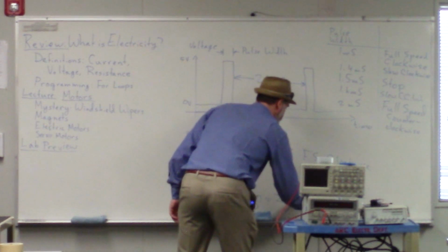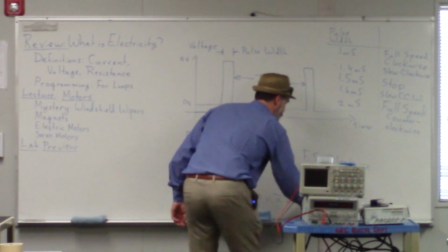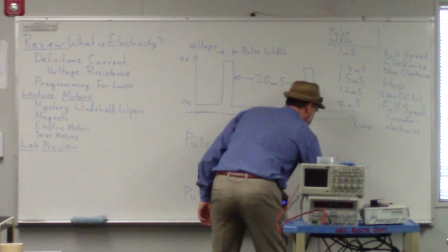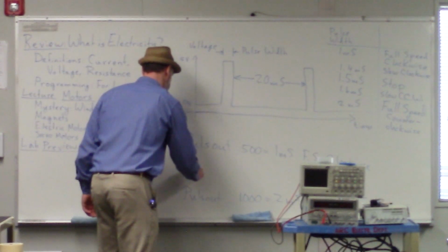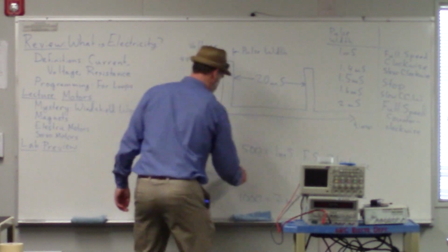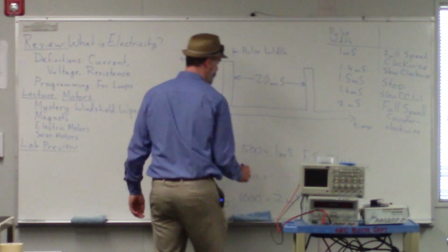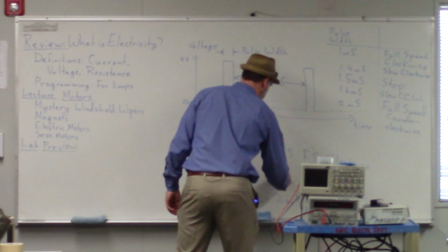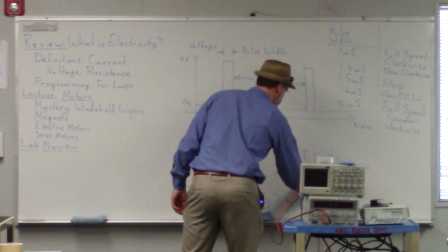So that's full speed counterclockwise. And right in between them is pulse out 750. And that's 1.5 milliseconds, and that's stopped.